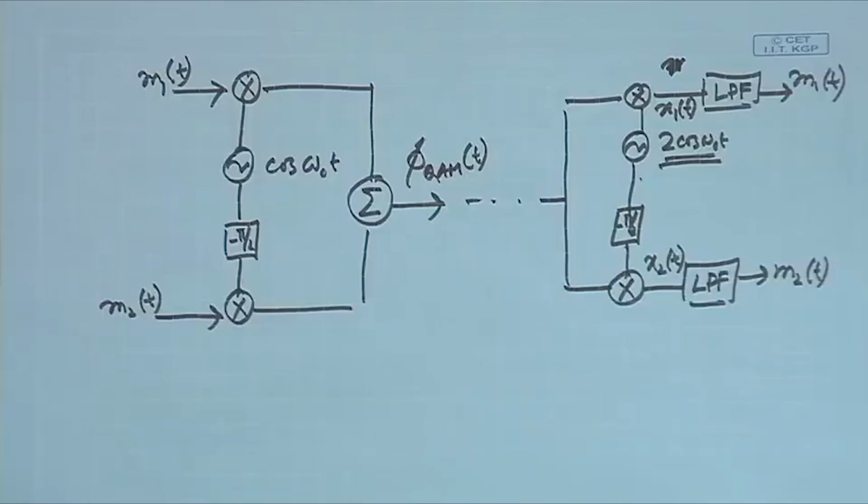Whatever we have seen so far, amplitude modulation is non-coherent, meaning there I can employ non-coherent demodulation. DSB-SC definitely requires coherent demodulation, because I have to multiply by the carrier. SSB also, if I do not put a carrier, requires coherent demodulation, and VSB also requires coherent demodulation. This one definitely requires coherent demodulation as well.